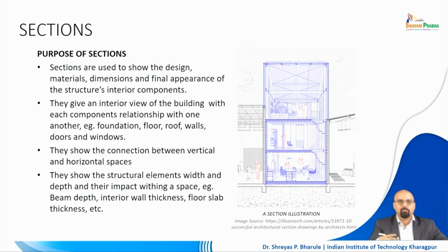We have talked about plans, elevations, site plans, electrical layouts, water supply layouts, all 3-4 different types of utility layouts, but still you want more drawings, right? You want sections, because in sections you actually represent the interaction of all of these different drawings, and sections are the drawings which can help you understand if something does not fit, right.